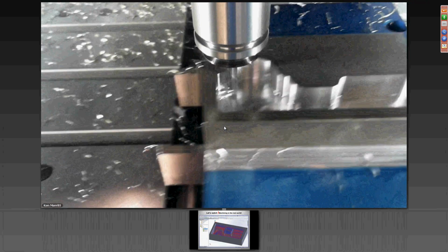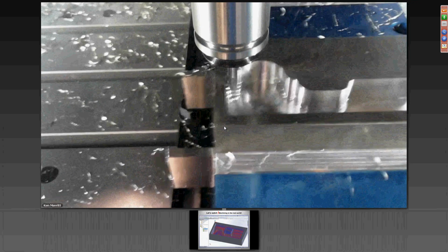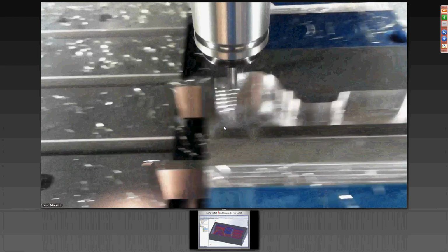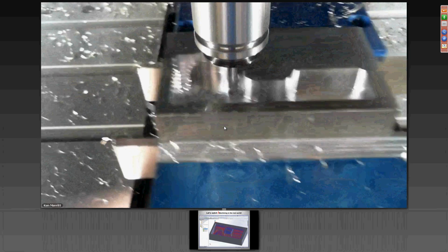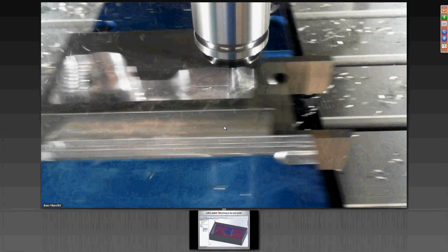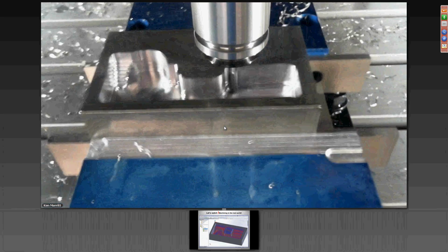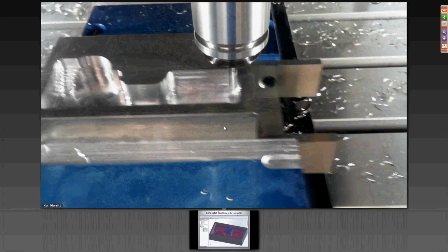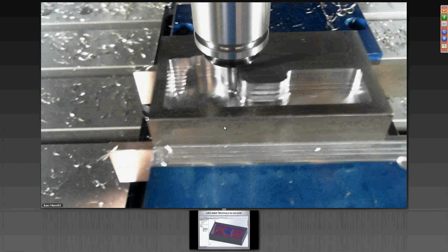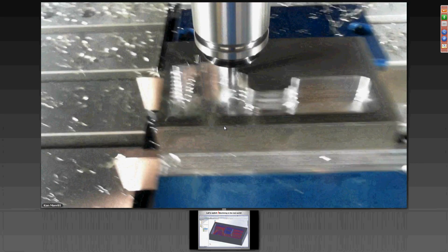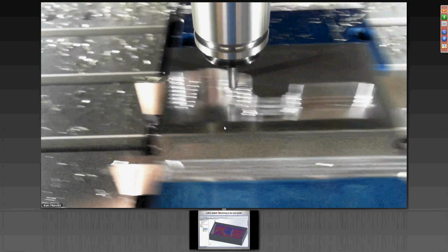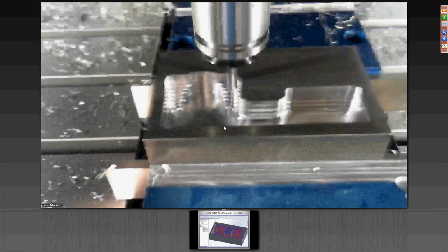Now, you may not think about this too much, but every machine, when it switches from G1 to G0 and from G0 back to G1, is going to pause for a moment. If you do that 1,000 times over a particular cycle, you've added quite a bit of time to your cut cycle. Okay? Now, what you're noticing going on here is what we call step-up staircasing. This allows us to create the 3D shape to a very near-net scallop height calculated by the system. We simply tell the system what scallop we want at the end of this, and it's going to take care of that regardless of the angle of the walls.